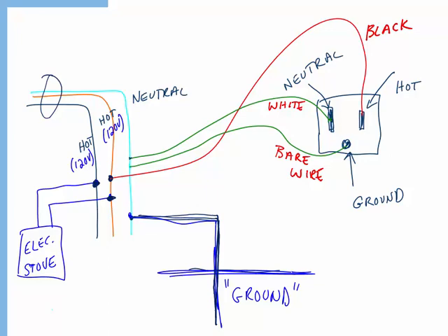All right, you'll notice that when we wire a three-prong outlet, both what's called the ground and the neutral actually connect to the same place in the breaker box. That neutral wire that's coming in from the power company is physically connected to a stake going into the ground right at your house. A little bit later on, we'll talk about why having this third connector, even though it's going to the same point in the box, gives you some added protection.